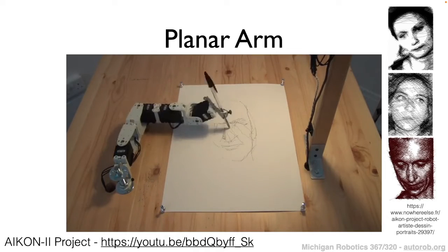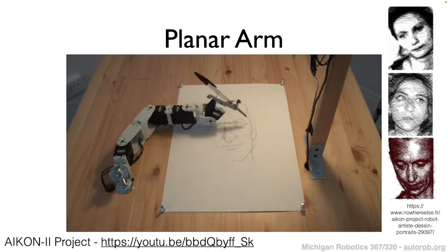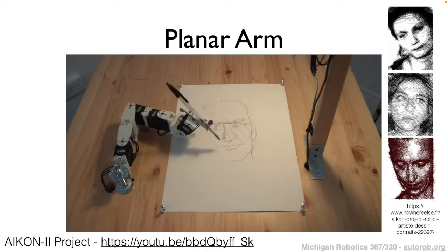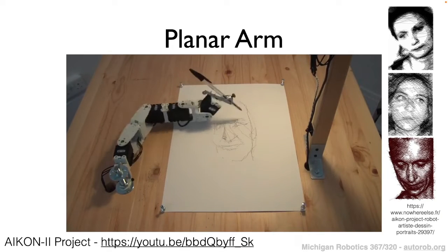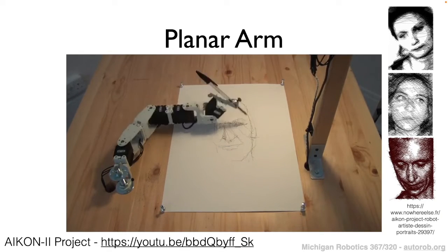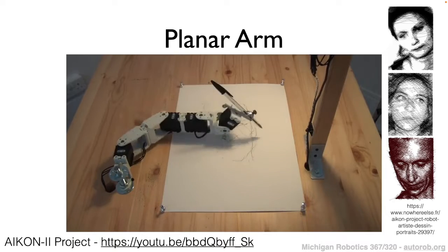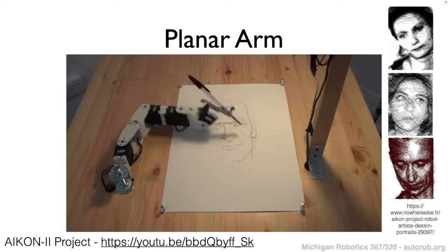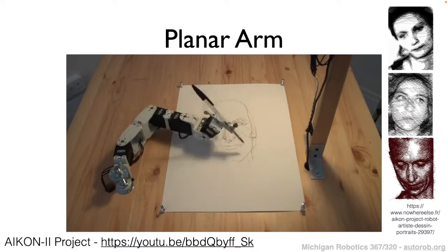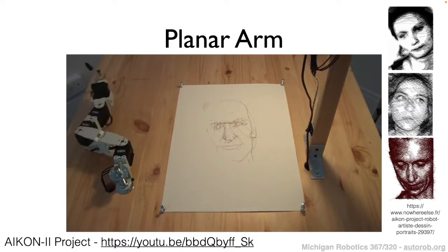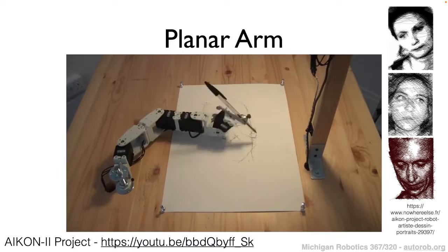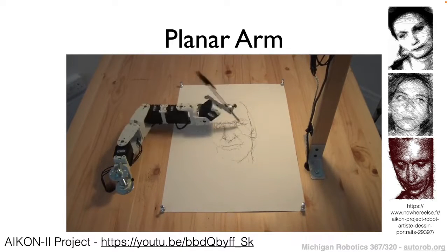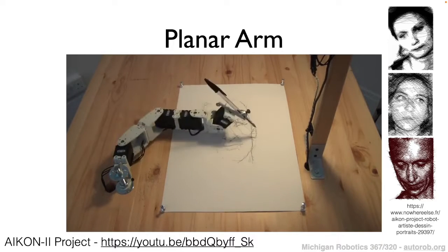If we focus in on the robotic arm, we could notice that if you ignore the wrist, which is actually controlling the pen to paper, the remaining portion of the robot is actually a two-link arm. It's actuated at the base of the chain, and then it has that elbow joint midway through the chain. Those two joints then make up what we could consider a 2 degree of freedom arm.